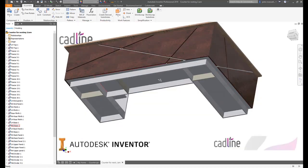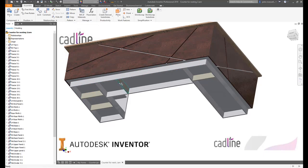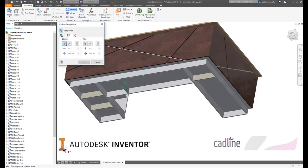If I stretch the model, my assembly is going to update, but you notice how all the parts are grounded, so I can't move them. But yeah, if I change the size of my source model, then all these parts will move automatically as well. So again, let's do the same for the right hand support. So this one I've got right hand support quantity and right hand support spacing, and this one here, pattern, I'm going to do middle support quantity and middle support spacing.